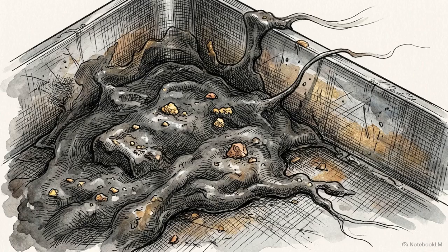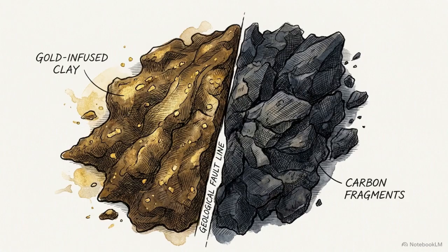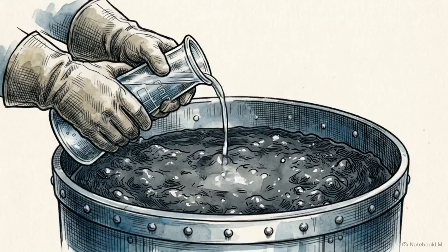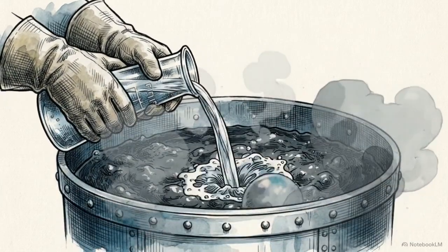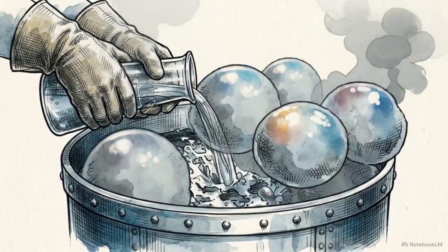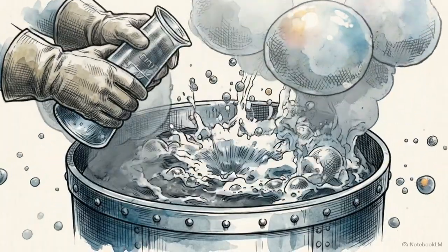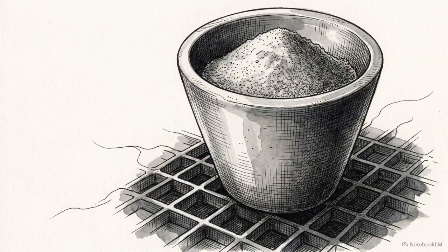The immediate physical output of the zinc displacement stage is a raw, unrefined material known in the industry as gold mud. This mud contains a gold concentration of only about 30%, heavily contaminated with residual unreacted zinc and other base metals. To strip away those base metals, operators utilize an intermediate purification step called pickling, which applies an aggressive acid wash to the mud. This prepares the material for the ultimate metallurgical upgrade, separating the pure metal from the final impurities via high-temperature flux smelting.